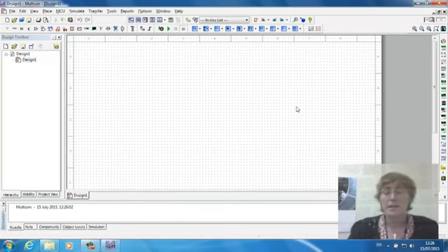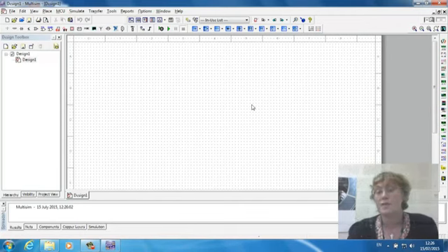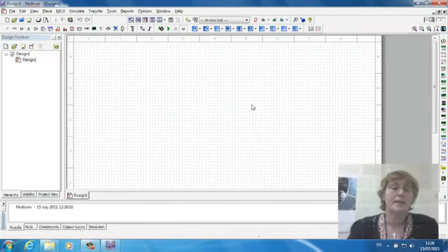Okay, now I need to make sure you have the same toolbars as me. The toolbars you're going to use are these blue toolbars here, which are virtual components. So that means that these are perfect components. They don't have any manufacturer tolerances built in. So the circuit we're going to build is purely to check the functionality. It's not to check things like how much effect does the offset voltage have, how much variation is there from one amp to another in gain. It's purely to check that the op-amp is working as an inverter.